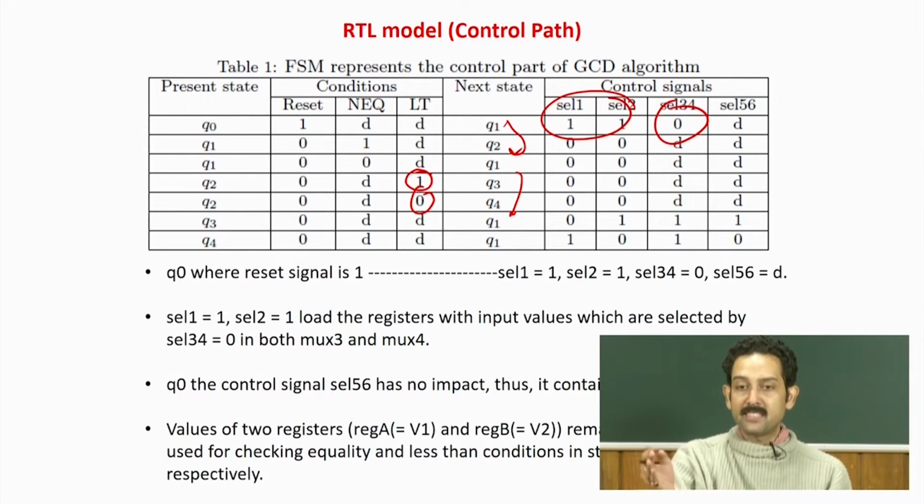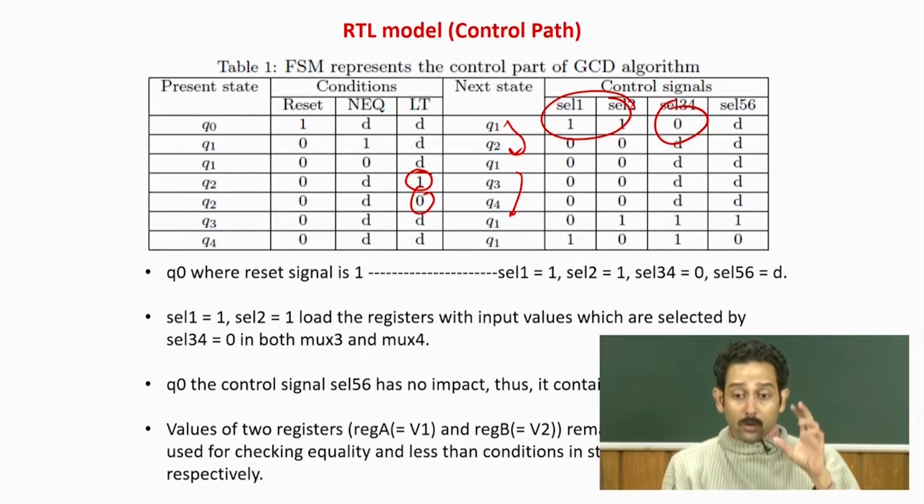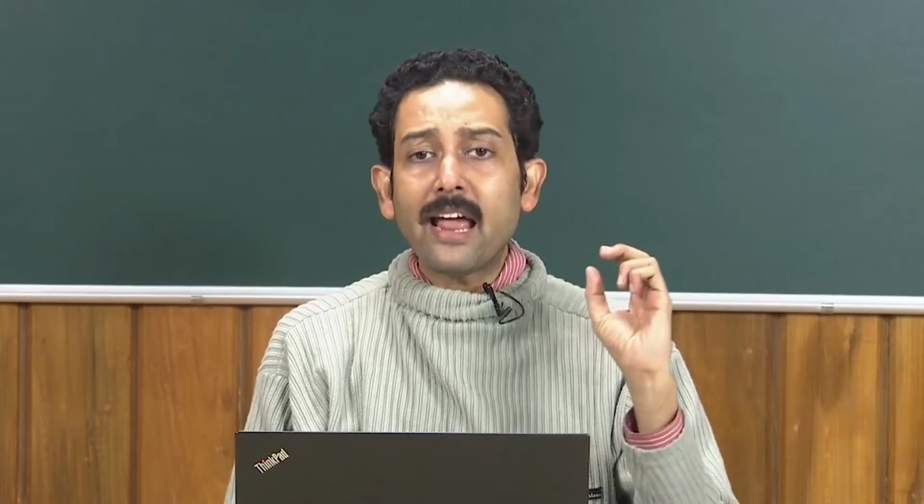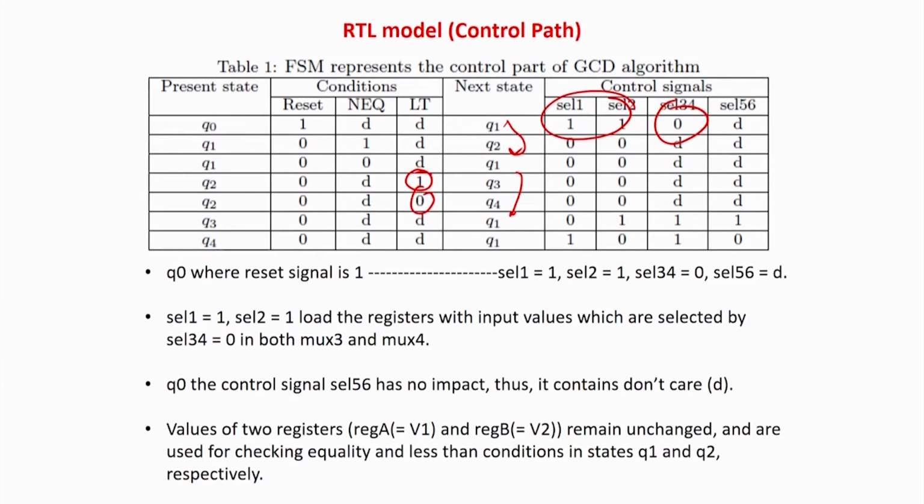If you make a combinational circuit using standard digital design fundamentals, you will find the size will not be more than 3 flip flops and around 10 to 20 gates. So testing of the control path at the abstraction level is possible, but not a real emphasis at this level. Really people are facing problems with the data path, so we will mainly concentrate on the data path in this case.